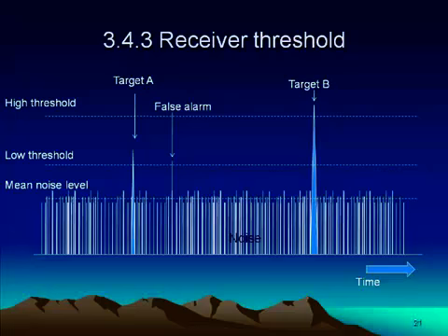If the signal is below this threshold, it will be ignored. So, how to decide this threshold is a very big question. It all depends on the location at which the radar is operating and the ability of the receiver to identify the incoming targets, etc.